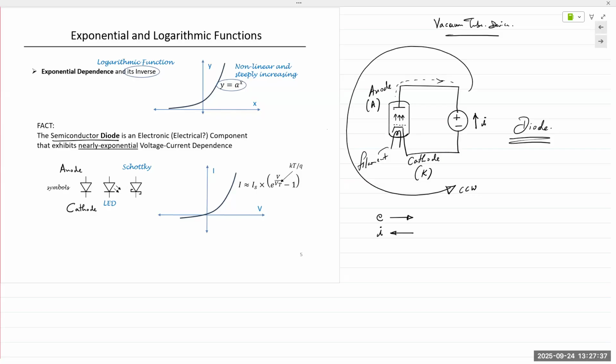And so when we heat it up, there is thermal energy that is imparted to that cathode. The electrons on the outermost orbit acquire sufficient energy from that thermal heat, and then they're able to break free and move. It would not happen with all materials. It will only happen with specific materials, right? We can heat up wood all we want. It's not going to become a conductor. Or you can take any insulator, like ceramics or glass, for instance. It's not going to impart sufficient energy for electrons to actually break their bonds, so they will never become conductors. Okay, yes.